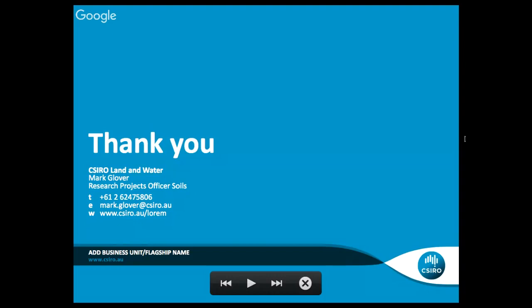The software has a pick list of a whole bunch of different instruments that it'll invert. It has mine on the list, but there's a whole bunch of Geonics equipment in there. The trouble is, the Geonics instrument takes an assumption that quadrature is a straight line and just kicks the conductivity off that. In fact, it tapers off. The in-phase one pops back down. Yes, it's the other way around, isn't it? I think I know where you're going with this.